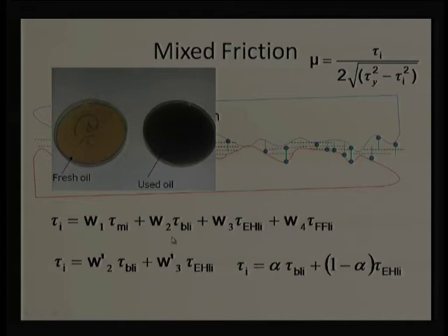Naturally, we will be using some sort of boundary additives, and whatever boundary layer is made, maybe it is made with chemicals, or the chemical layer is made as a bonded lubricant layer, not only a solid lubricant, then this kind of color of the liquid lubricant will emerge. That is obvious. Even when chemistry is happening, obviously chemical action is happening, or when we are talking about some sort of chemical layer on the gear pair, naturally some metal is going to react or get oxidized, and when it is removed, naturally it is going to make a color like this. So, that is important to consider.